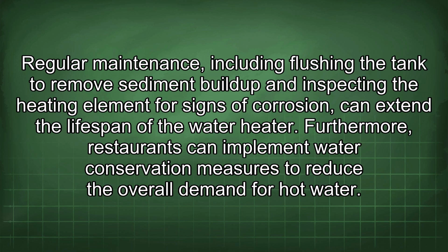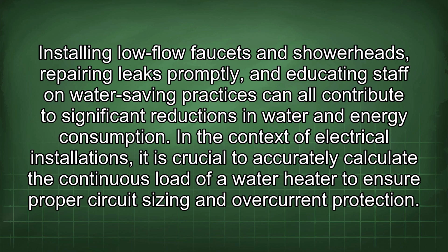Regular maintenance, including flushing the tank to remove sediment buildup and inspecting the heating element for signs of corrosion, can extend the lifespan of the water heater. Furthermore, restaurants can implement water conservation measures to reduce the overall demand for hot water. Installing low-flow faucets and shower heads, repairing leaks promptly, and educating staff on water-saving practices can all contribute to significant reductions in water and energy consumption.